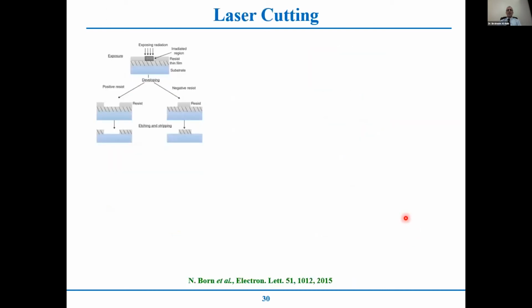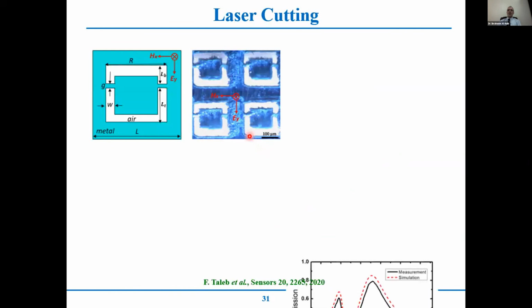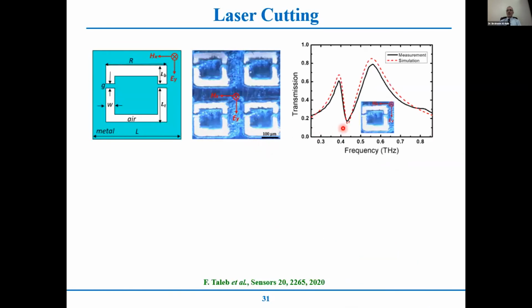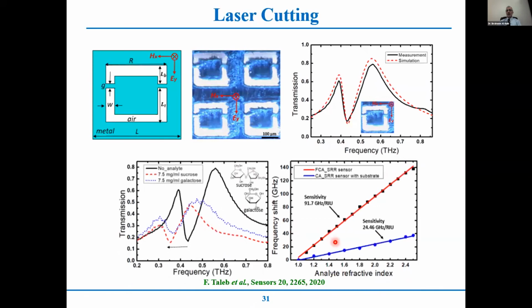What you can do here, actually, is fabricate these structures not only with lithography, you can build your own system using a nanosecond laser, and just take some aluminum foil from your kitchen and make complementary resonators, and it actually works. And the performance of such is not too bad compared with the cost, so you can use it for sensing. And the nice thing here, when it comes to complementary, we call it a freestanding structure, it has much better sensitivity, actually more than 3 times, because there is no substrate at all here.